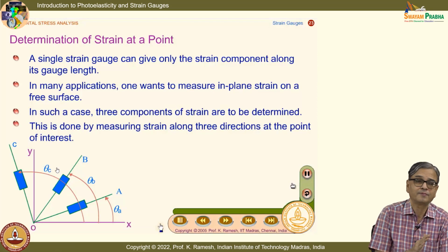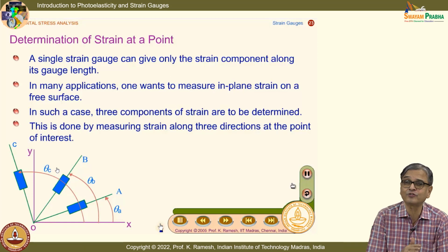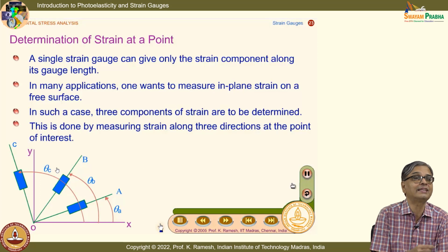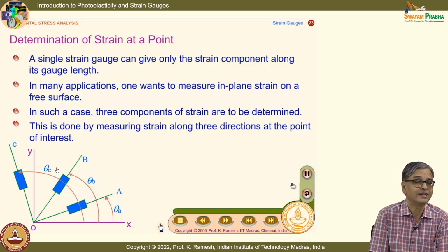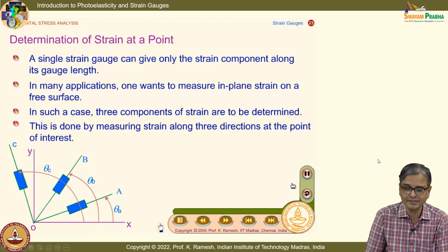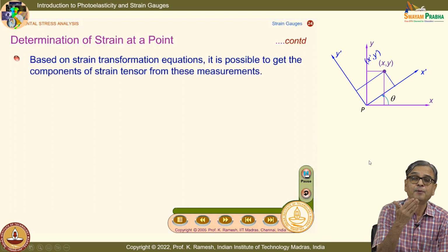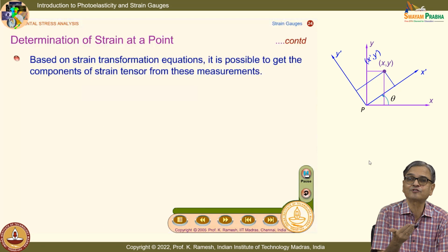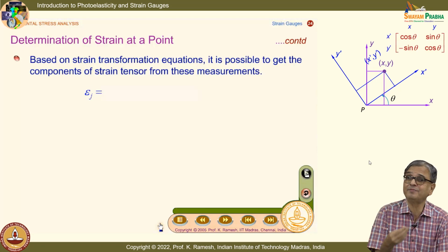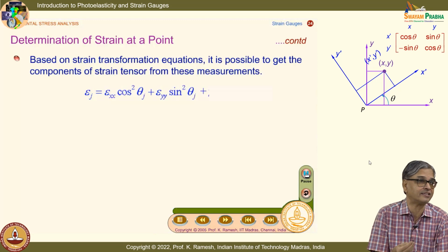I told you transformation laws are very, very important. You cannot afford to forget them. You should be able to write them very comfortably. Fine. You find an application in the case of strain gauges. So, I can go and find out what happens, and thankfully the strain gauge manufacturers put 3 strain gauges on a backing and supply it to you, and this is called a rosette, because aligning it on a field is extremely difficult. You have pre-aligned strain gauges.